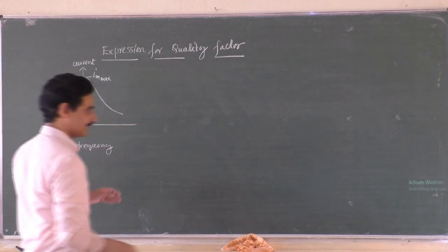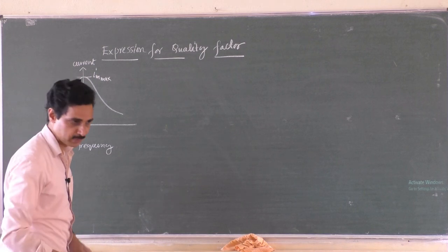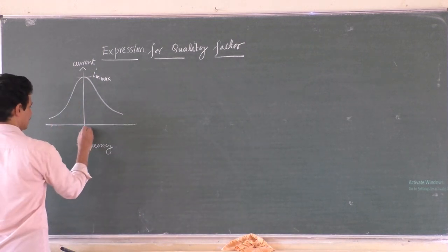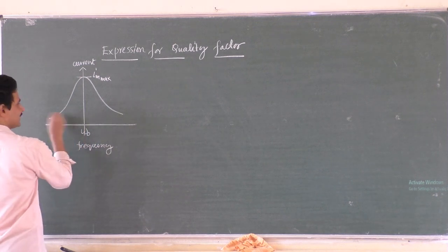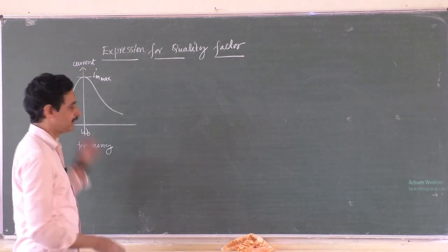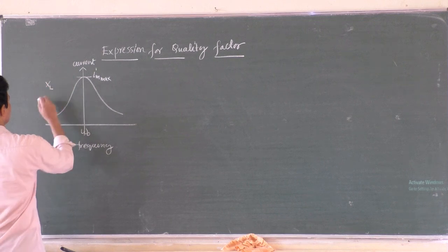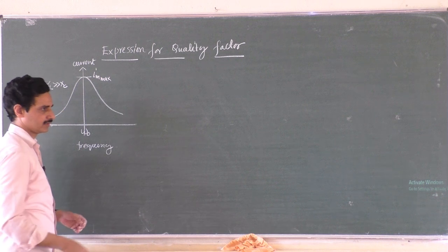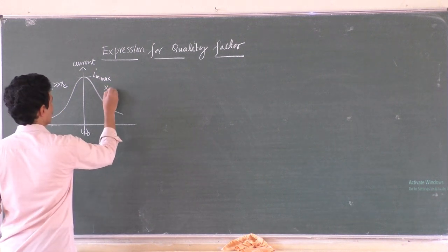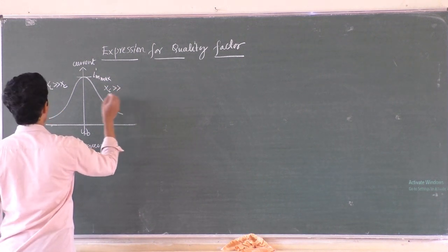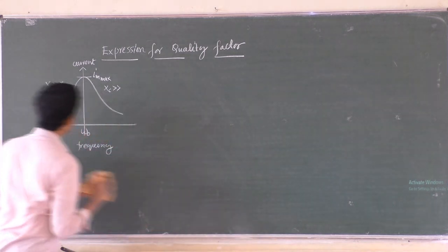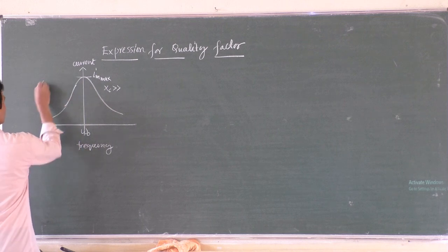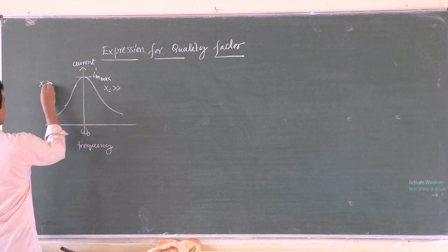When the frequency is lesser than the resonant frequency, you know that current is less. That is because of the problem from the inductor. Inductive reactance will be much greater than capacitive reactance. At all the frequencies greater than the resonance frequency, the capacitor blocks and XC will be much greater than XL, because XC is 1 by omega C.